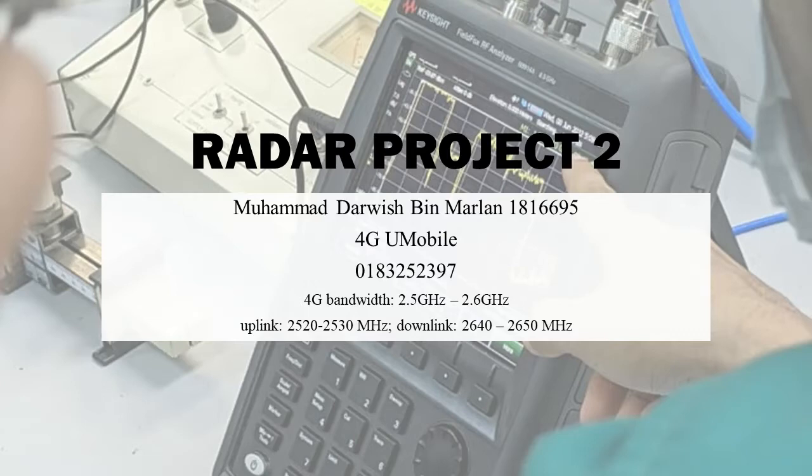So for this project, my assigned network technology is 4G. The uplink and downlink frequency for 4G is: the uplink is 2520 until 2530 MHz and the downlink is from 2640 until 2650 MHz. And the bandwidth assigned for 4G by MCMC is from 2.5 GHz until 2.6 GHz.